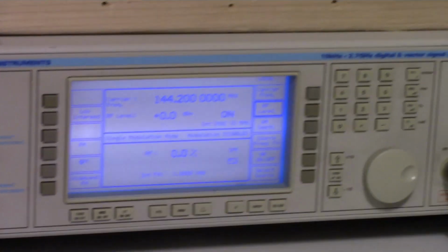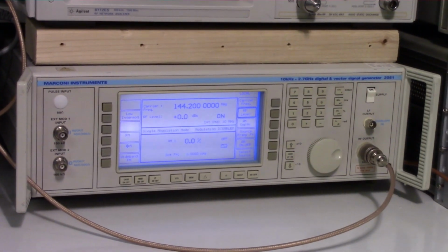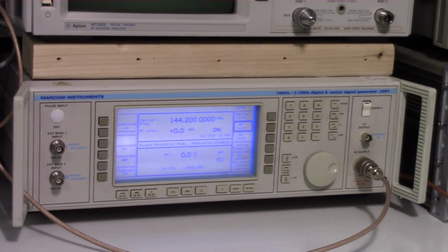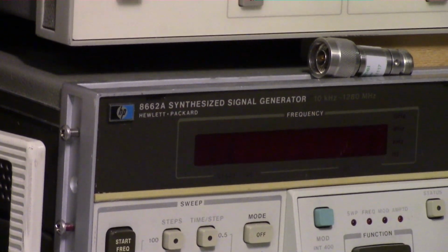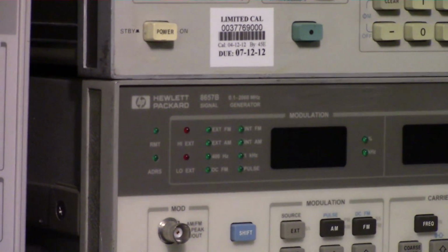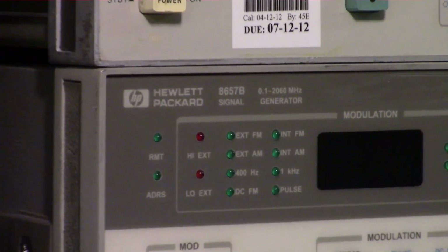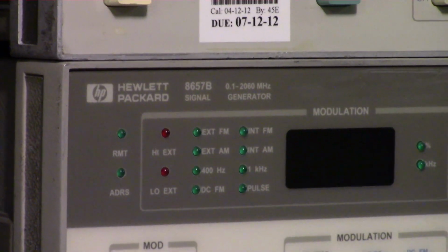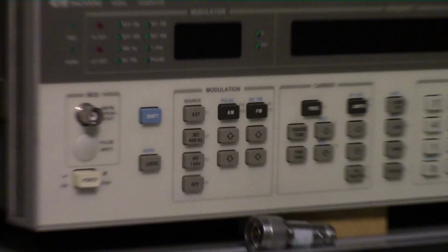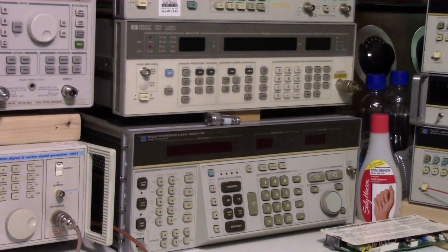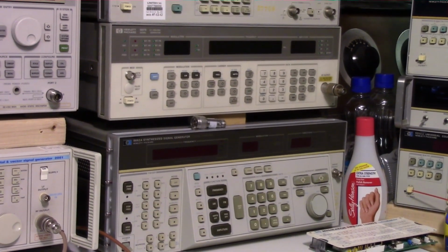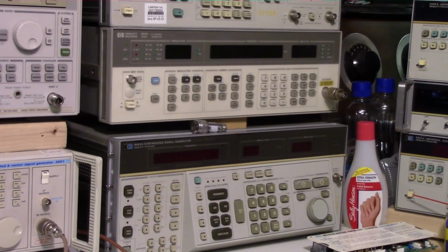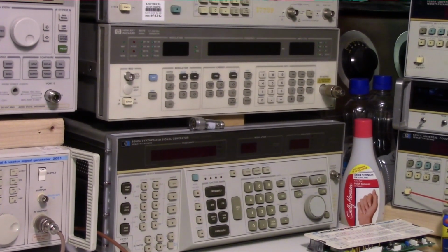Every signal generator, regardless of their cost or make, whether it's a nice Marconi like that, or even something like an 8662, which is a really nice Old Faithful, or something nice like an 8657B signal generator, has this issue. When you start dialing in lower and lower amplitude values for the RF signal, the tolerance of that amplitude starts getting to be a little bit sloppy.